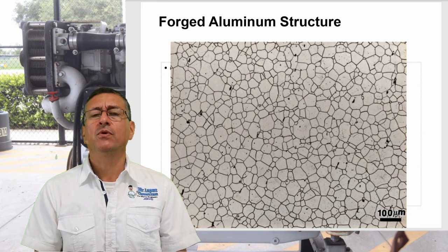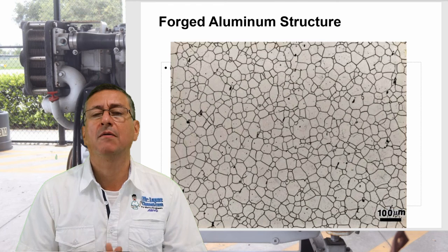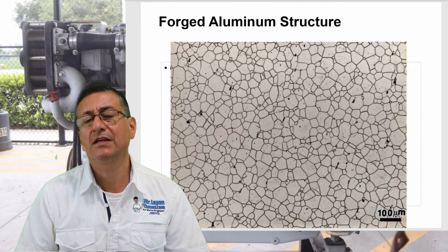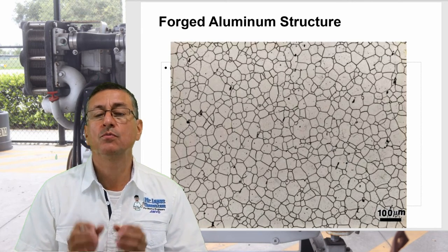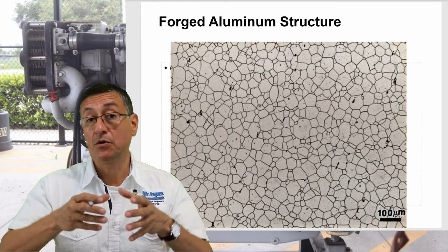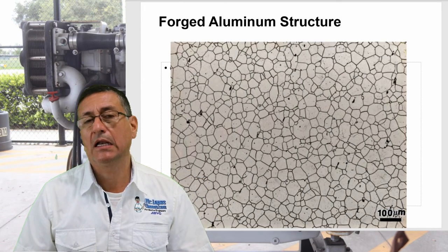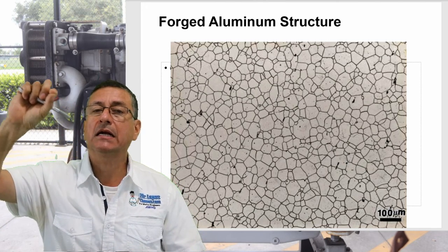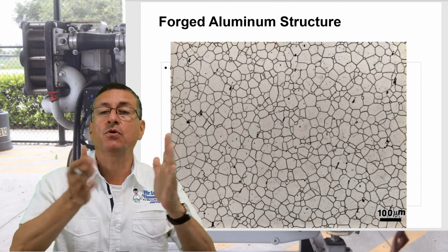What is the problem with the bubbles internally in the piston? We are going to talk specifically about the bubbles inside of the piston. If the structure of the piston is cast material with too much air, too many bubbles, when the temperature of the piston increases, the diameter of the bubbles increases, and it's possible that those bubbles expand, cracks propagate, and from fatigue, suddenly the piston breaks.